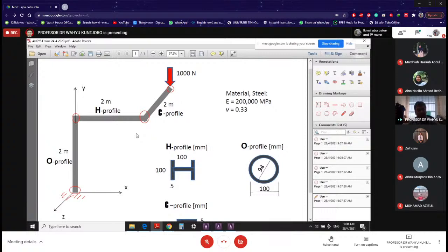This is sufficient actually. But I want it to be probably slightly more accurate. So in between, I want to have a node exactly at the mid between this node and that node. Also over here. Okay, I can just do it like that. And finally, also over here.